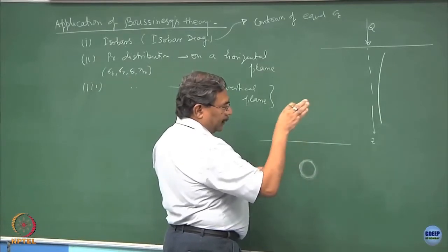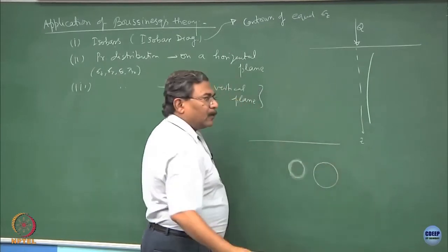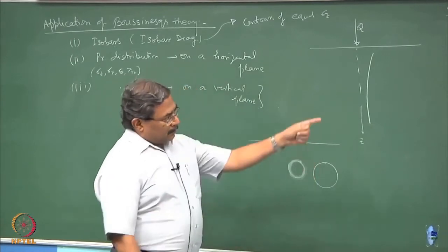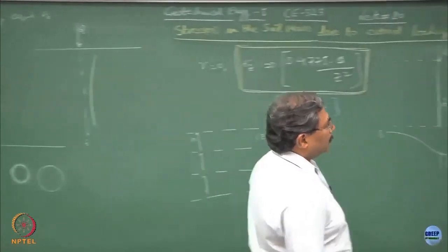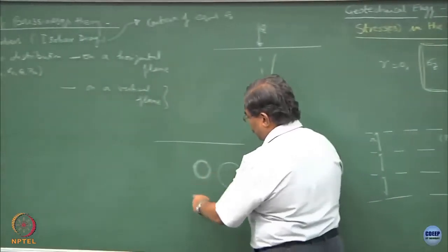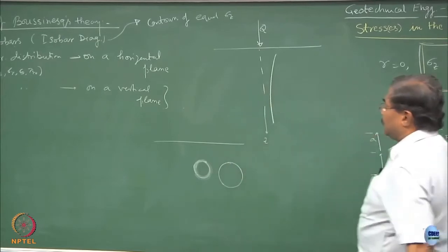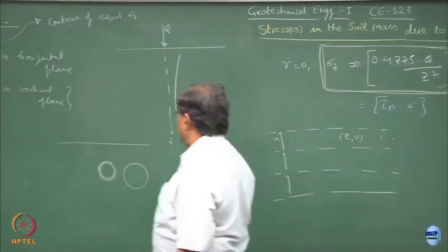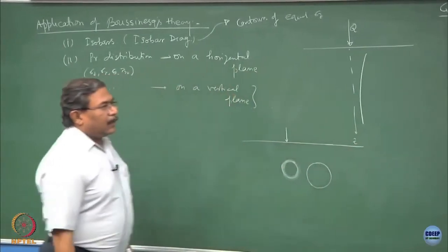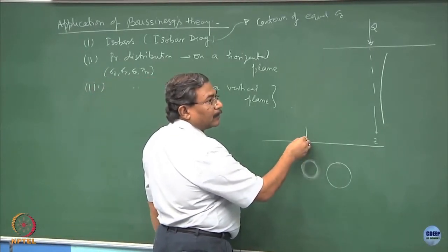That means the landing and taking off operations are occurring, and you would like to take out some utility across the runway. Simple analysis like this can help you. I can define the zone of influence of the pressures, and I can negotiate by locating the pipelines there. Every time I cannot be so lucky, so then you have to do engineering based on the material properties and whatever. Anyway, giving you an example, suppose this is how the load comes, alright, and I want to see whether this pipeline is going to get influenced because of the external loading or not.